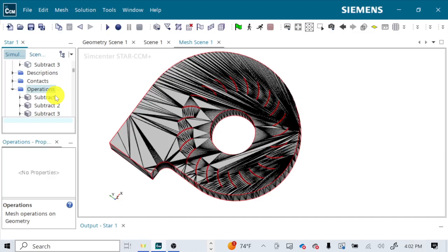A subtract will be where they do not overlap. A unite will be where any of the parts exist. So you can kind of think of these as logical operations, which is why they're called Boolean. It's because they effectively are logical operators in that sense. At least some of them are.